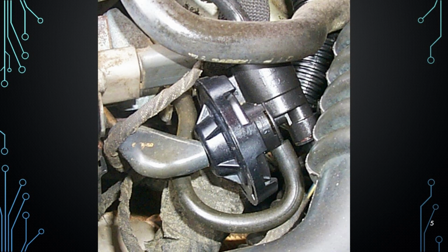This sounds like an EGR, exhaust gas recirculation, backpressure transducer, or a similar EGR control device. In older systems, these units help modulate EGR flow based on backpressure. The round piece often is a diaphragm that senses exhaust pressure, controlling EGR accordingly. That is correct. Actually, the electrical portion is just simply an enabling solenoid, so it doesn't work till that's turned on. But once that's energized, once the engine reaches a specific temperature, then that modulates, just like was stated there, the amount of EGR flow.